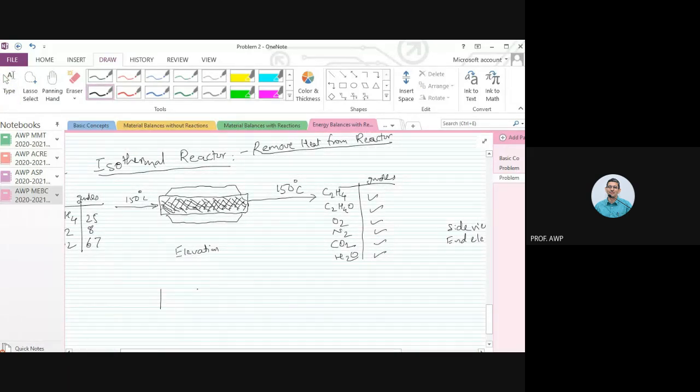If you have an isometric, L, B, H, if you look at it in plan, so plan means view from the top, it will look like a rectangle, L into B, this is your plan. If you look at it as elevation, it will be another rectangle, but L and H. If you look at side view or end elevation, it will be another rectangle, B into H.